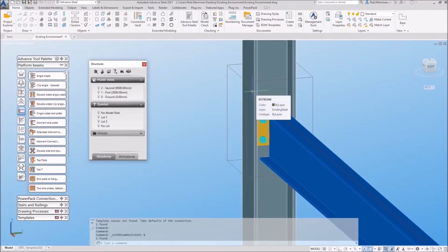It does work quite well. You do have to be a little bit careful with it sometimes. Say, for example, we've got a shed and we have some purlins on there. At the end frame you would just use a single-sided purlin connection, but in the middle of the frame you would use a double connection.